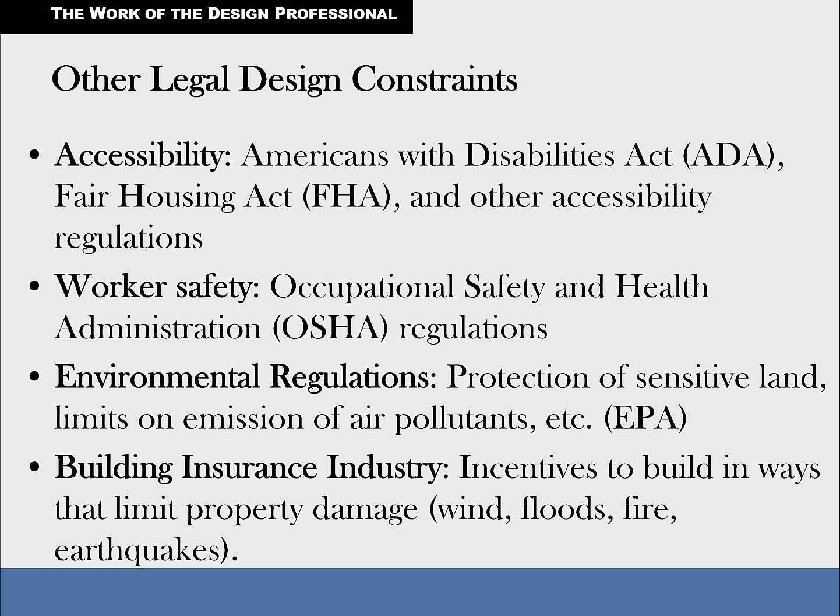There are environmental regulations from the Environmental Protection Agency on emissions of air pollutants and water, and soil erosion while you're doing the construction. So you've seen in construction sometimes 1-foot high silt fences that are just keeping the wind from blowing the dirt off the property. When you've stripped all the topsoil, you've got nothing but dirt. It gets dry enough, then it can blow off in just a big dust storm, or run off in a rainstorm into the city runoff system and clog it all up too.